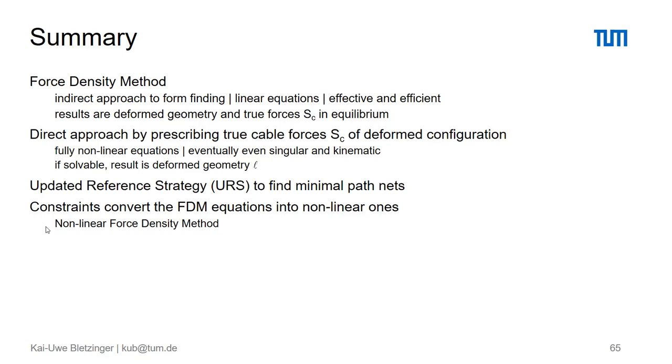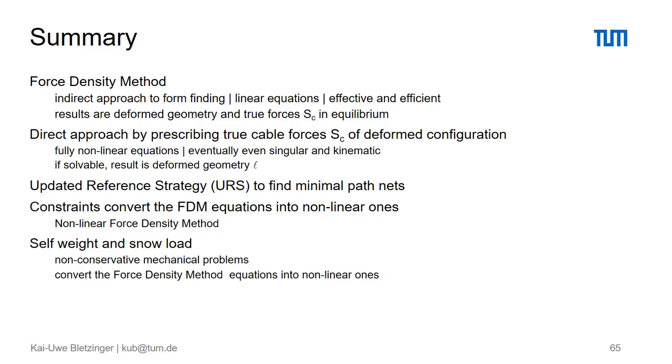If dealing with self-weight and snow load, we recognize that we have to deal with non-conservative mechanical problems. As a consequence, the stiffness matrices are asymmetric. And again, these kinds of load cases convert the force density method equations into nonlinear ones.